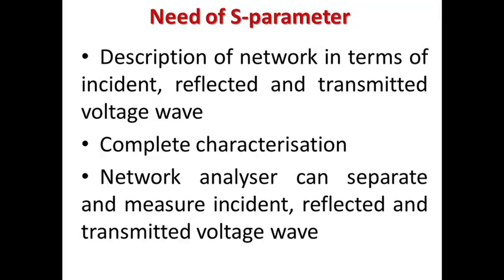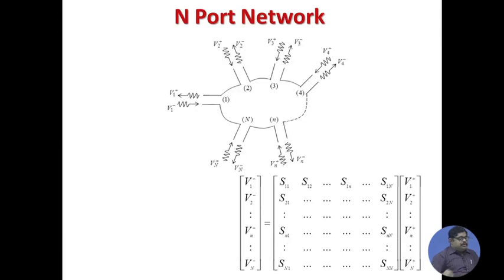For measurement, this is the way: if you have a microwave network, you either measure or estimate the S parameter, and convert S parameter to other two port parameters. So, any of them can be used. That is the popularity of S parameter, which we are calling the second tool of a microwave engineer.